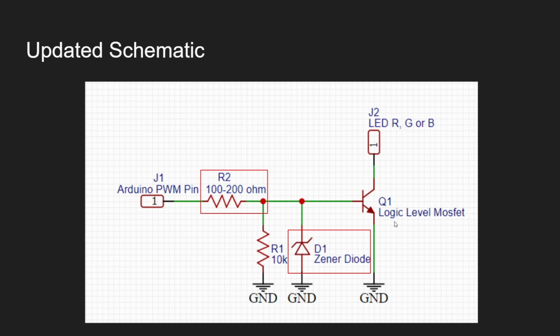These MOSFETs apparently can be quite demanding, and sometimes without this resistor, the draw can be more than what the Arduino is actually spec'd for, and that over time will damage it and cause premature wear and death. For the circuit we created, for my application, I didn't add it in afterwards because it's not really needed, just because it's only a test thing, but best practice would be to add this in if longevity is important to you.